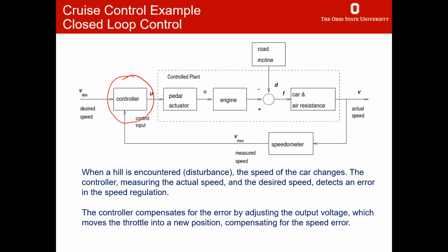You probably have not used any of the old cruise control systems. They used a proportional control, which meant that if you switched it on with a large change in desired speed, it would actually overshoot and then do a couple of oscillations. So you had to be extremely careful because they were built mechanically. They were not built electronically, and you would really experience that, but it was still very nice to have that function in your car. You have to be careful. Nowadays, of course, it's all electronic, and the car will not just jump around. It's going to smoothly go to your desired speed once you enter the new set point change.